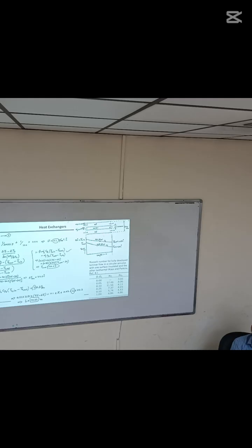So the critical thing is the evaluation of the convective heat transfer coefficient. You can see here the convective heat transfer coefficient for one fluid is only 39, for the other fluid is 3000, right? So if we use wrong Nusselt numbers, or simply use assumptions, this will be affected. At the end, you are paying for this. Either you will get a very small value or a very large value if you start making assumptions here for convective heat transfer coefficients. Okay,